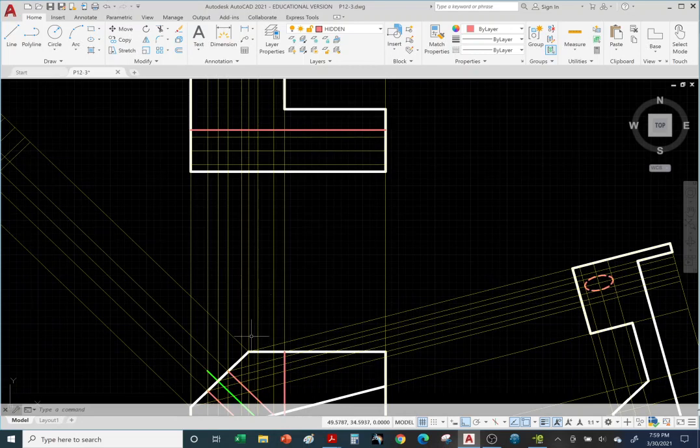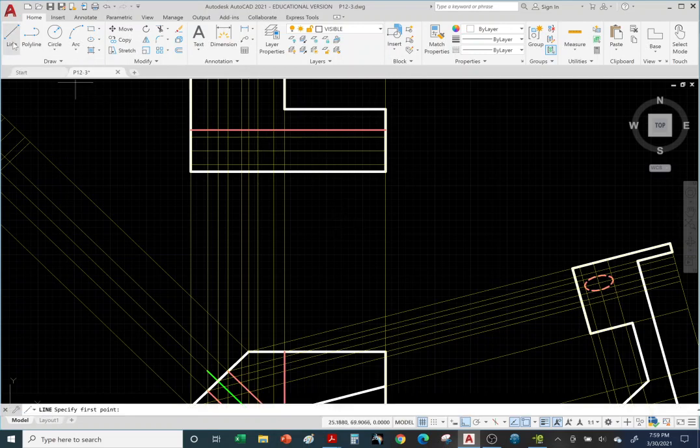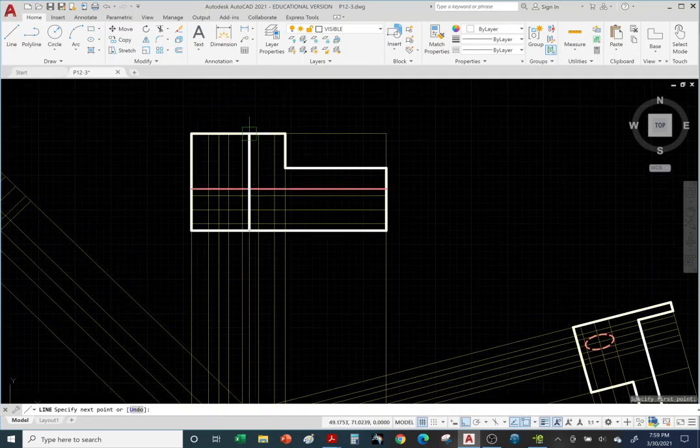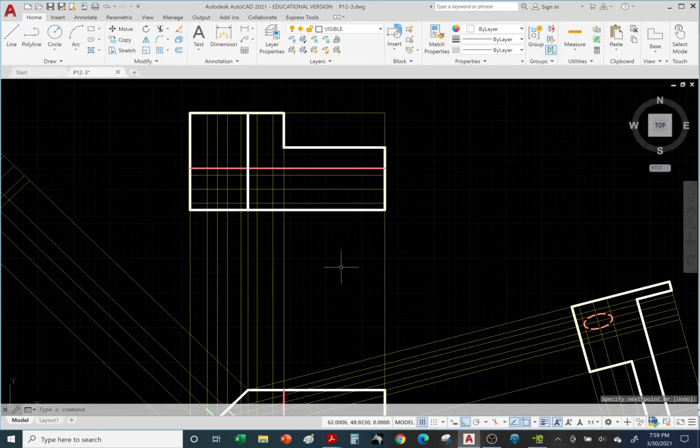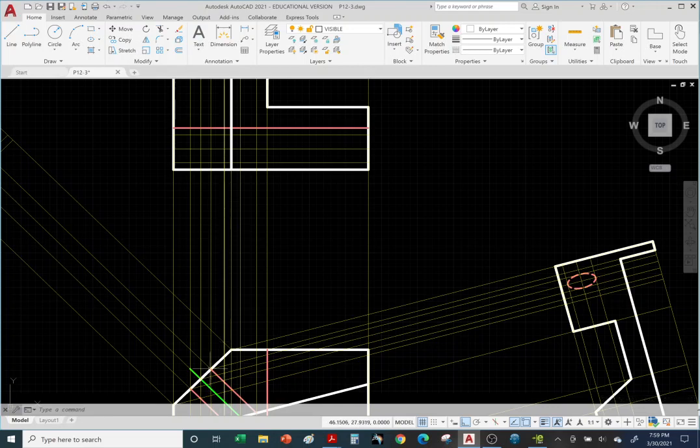Now we have an object line from this vertex. Line command, visible object layer, from this vertex go straight up. Click. And there it is, right click enter. So it looks like we have everything in the top view except the hole. This one's a little bit tricky.